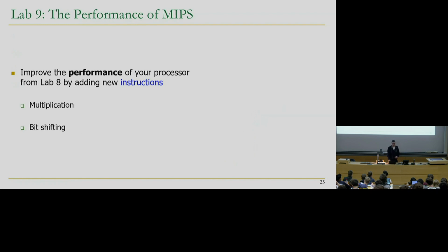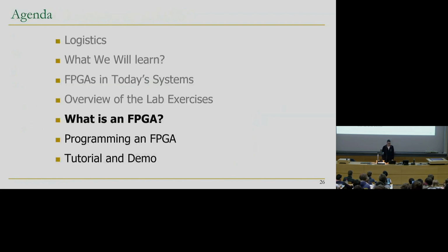Okay, but before that, to do multiplication, for example, you'll be using different operations, right? You can use addition to do multiplication with multiple iterations. So instead of that, we will be implementing a multiplier unit to make the processor do multiplication faster.